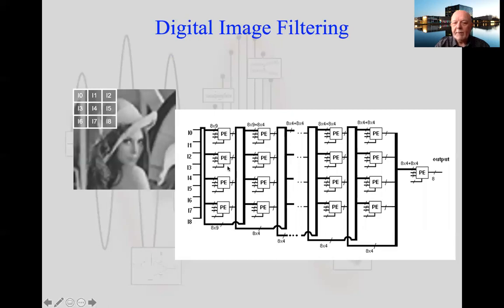We'll see in a minute what these cells look like in some detail. They've got connections back, and in this architecture, they go back two columns. So the first column just has inputs connected to it. The second column has inputs and the outputs from column 1, etc. As we go down, we've got an output at the end here.